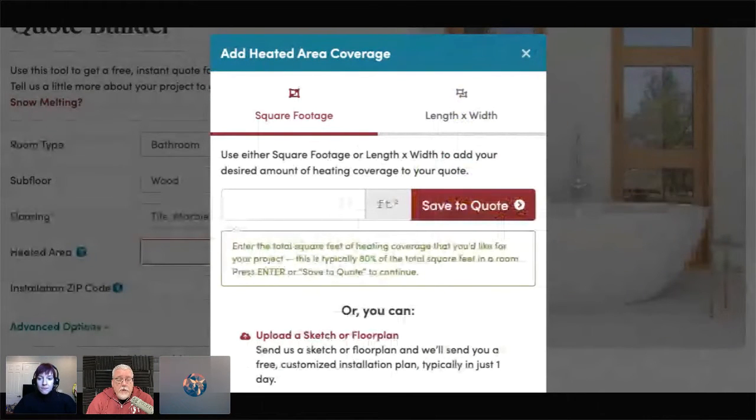That's where 20% of your space in that room is going to go: permanent fixtures, air vents. If you're doing plans, always remember to put the air vents or any posts that might be in the room, especially in a basement, because it has support posts. You have to go around them and you can't count that as square footage. So think about what would interrupt the floor surface. That's about that 20%.